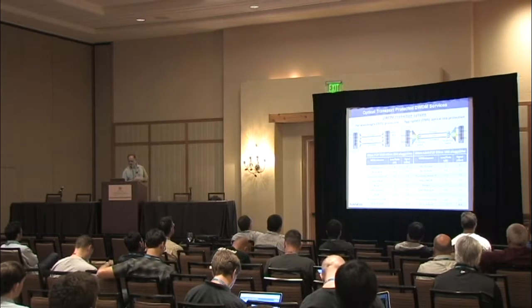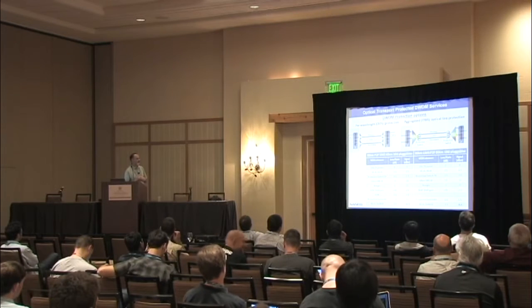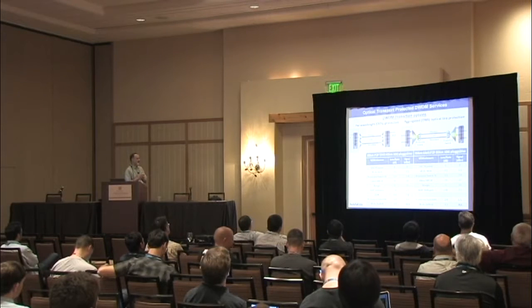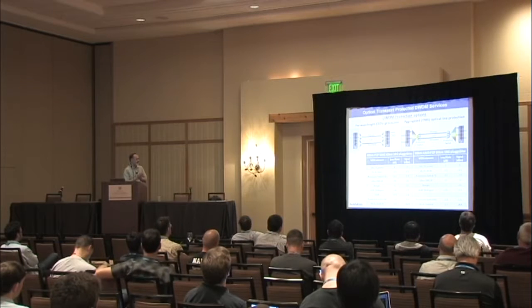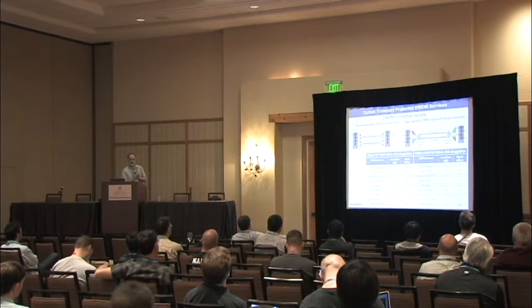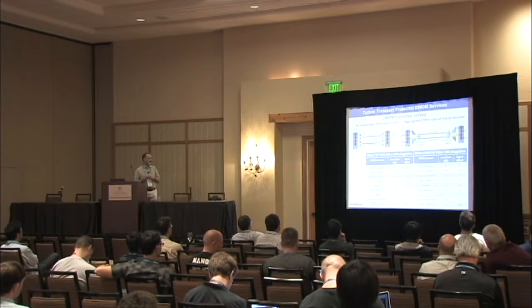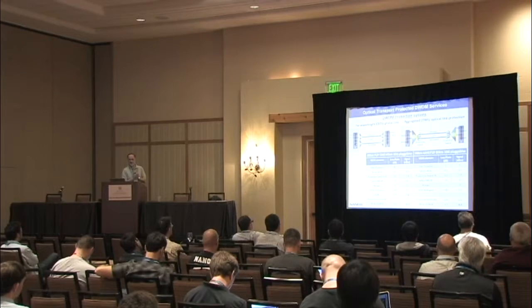So going over the calculation, and you're already used to this, start at 0, the Mux minus 3.5. The protection switch by itself induces on the transmit side minus 3.5, we're at minus 7. 60 kilometer of fiber, we're at minus 22, margin of minus 23, and we're adding an amplifier of 20 dB, we are back at minus 3.5. Now the DCM, the minus 3.5 insertion loss of the DCM that you've seen already, and then the protection switch on the receive side, it's about minus 2 dB, we are at minus 9. The 40 channel Demux, minus 3.5, we are back at minus 12.5, within the range of the transceiver.